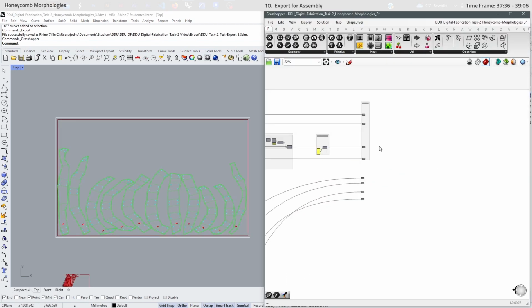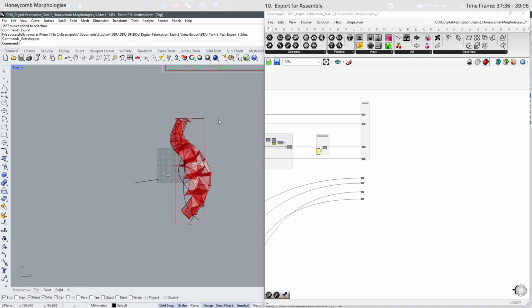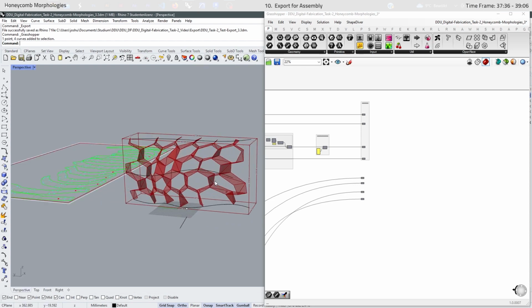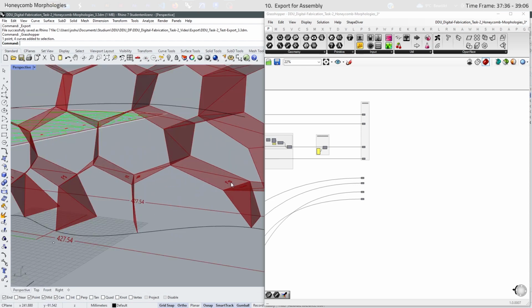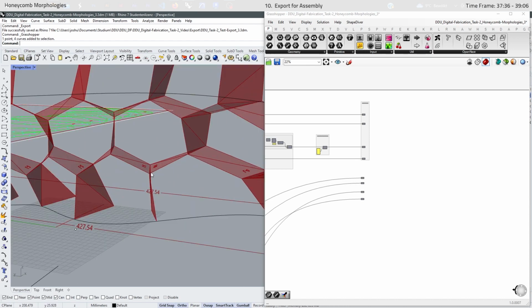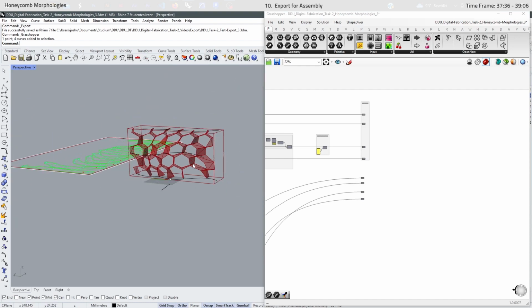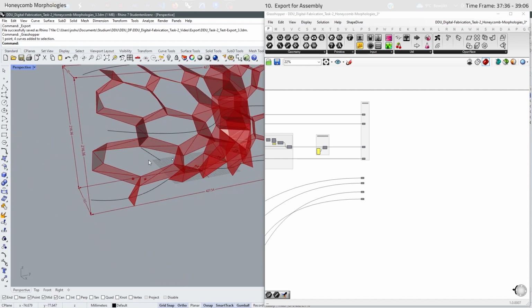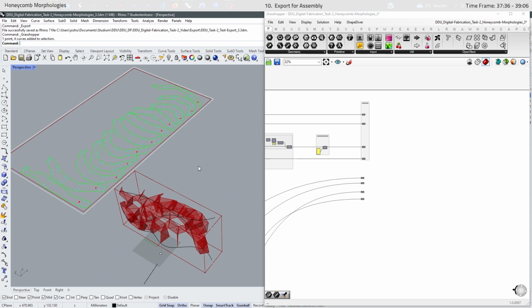And also make sure to save your other Grasshopper file and other Rhino file with these curves right here, so that when you assemble this geometry, you can orient on the markings right here and know in which direction you have to fold. This is very important. Don't forget this. And name all these files similarly so that you find which file belongs together.